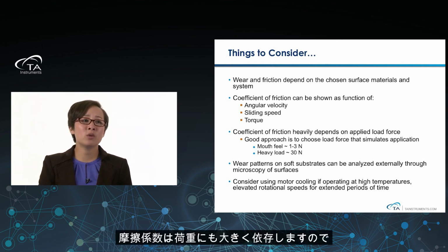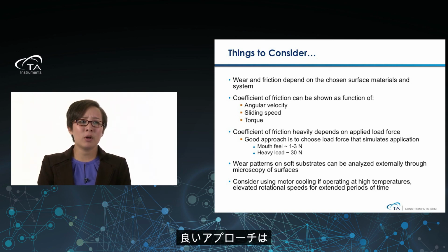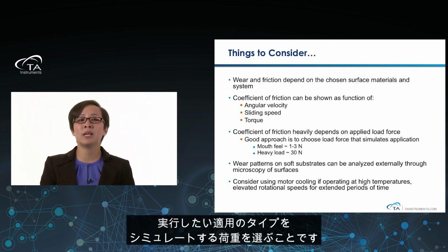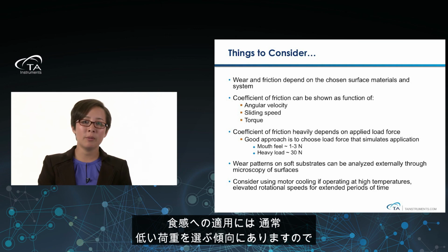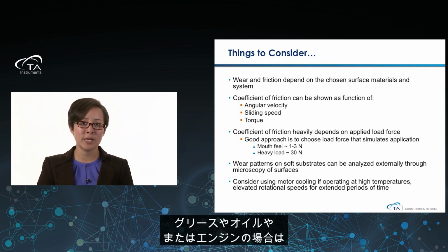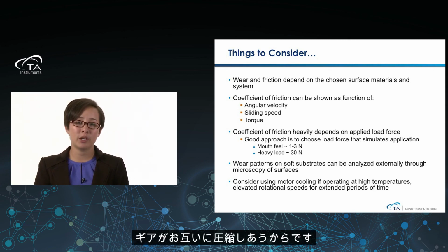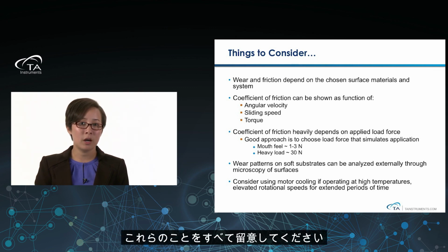The coefficient of friction will also heavily depend on the load force. So sometimes you think, well, what load force do I use? I'm not really sure what I'm doing. A good approach is really to choose the load force that simulates the type of application that you're doing. So for mouthfeel applications, we typically tend towards lower load forces, like 1 to 3 newtons. Or if it's something like greases and oils in engines, maybe we're looking at more of a heavy load, because those gears are really going to be compressed against one another. So these are all things to keep in mind.